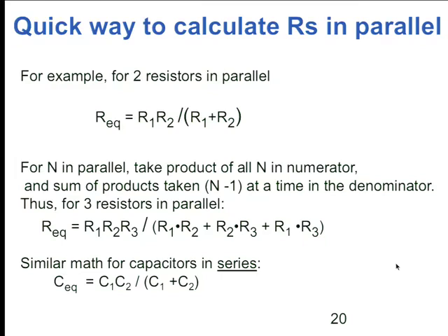It should be, as we said, divided up across these two resistors. Now this one is 3,000 ohms. This is 1,000. So this is a bigger resistance. It's going to suck more energy out of the 13 volts. In fact, it should be in a ratio of 1 to 3. So this one should be, oh, that's around 10. So we're missing 3. This one should be about 3.